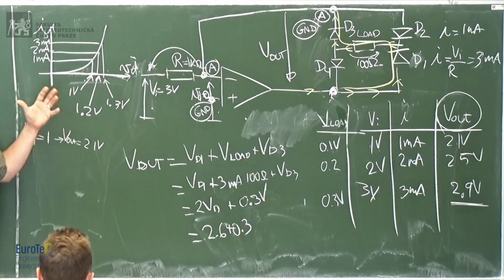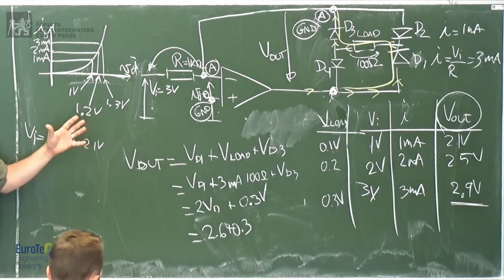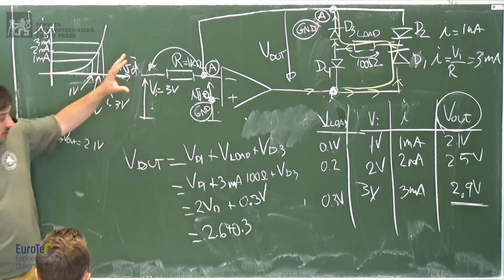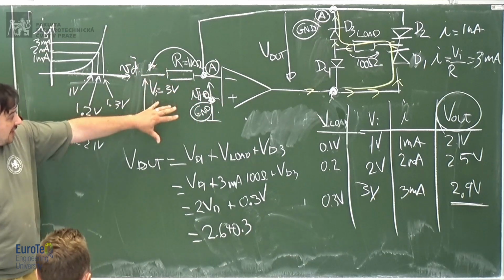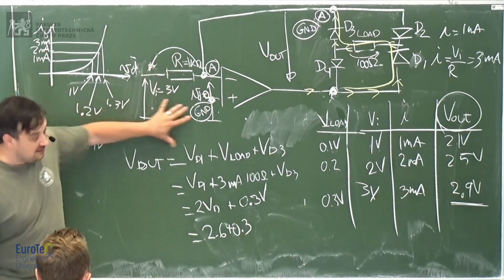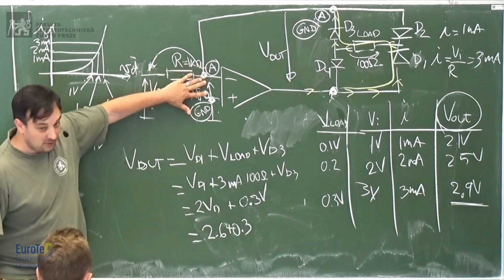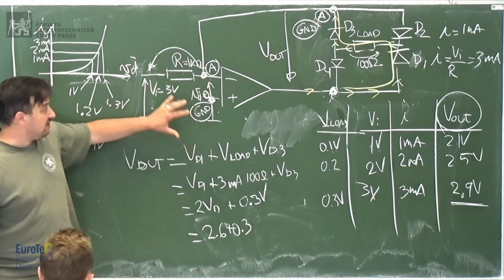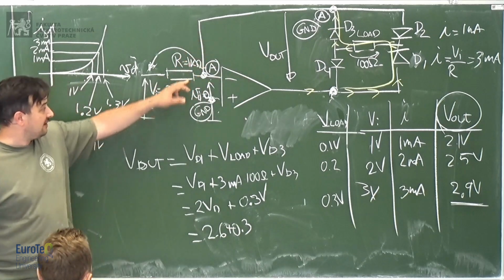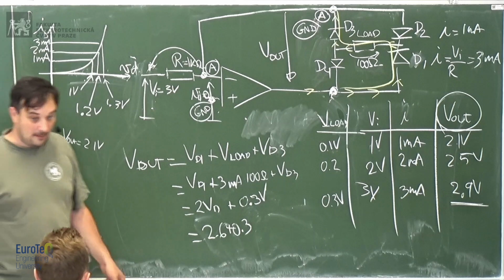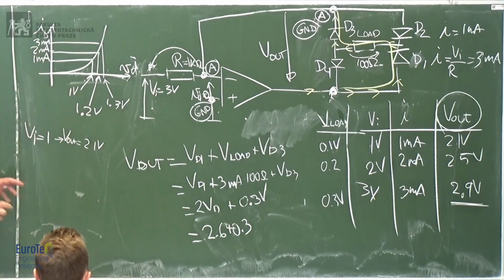But it doesn't matter. The operational amplifier is smart enough to say, I will generate the correct amount of voltage at my output so that this equation here holds. I always have here the voltage equal to 0, which means that the current will be the exact current which flows here, V1 divided by R1. Understood.